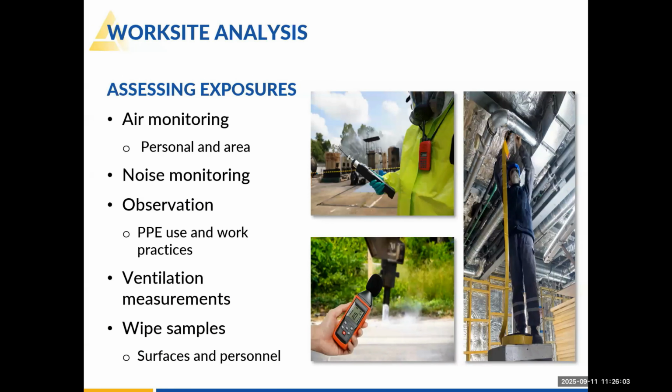So how do we determine what levels of exposures we have in the workplace? We need to do a work site analysis to assess those exposures and to determine what's our baseline. What are we basing it off of? We'll do air monitoring to include personal and area sampling. Let's say you've got some welders, they're exposed to welding fumes.